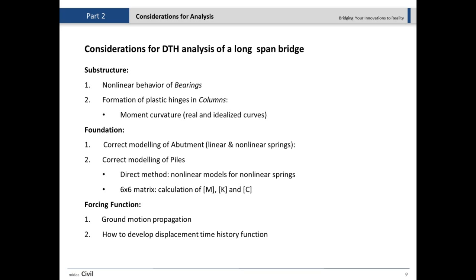For the foundation, we're going to talk about the methods that are available for modeling the abutment, or modeling the soil behind the abutment, because that's pretty important. If you just ignore those, for example the soil springs, you're going to come up with a completely different response of the structure, which might not be what you are looking for.